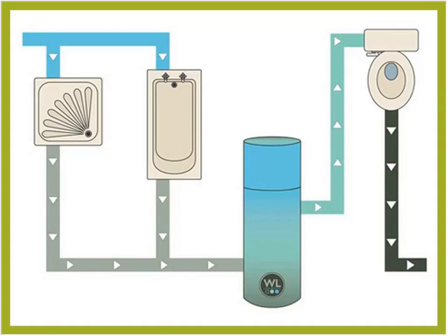But Graywater is definitely an interesting topic. It's the whole idea of taking your bath water and your sink water, again, your bathroom sink, not your kitchen sink, where you've got black water from organics, and it goes into some sort of filtration device, and then that goes right into the toilet, and then that toilet water can be flushed from the Graywater, and of course you can see it becomes black water from there. That is an easy way to reduce your water demand, but again, it can be more costly and expensive to retrofit these types of systems in the home.